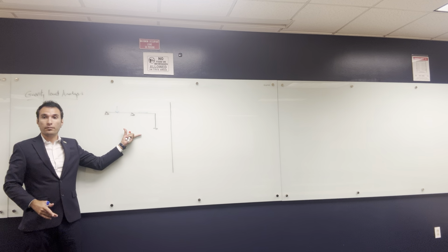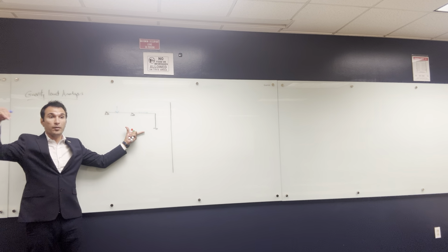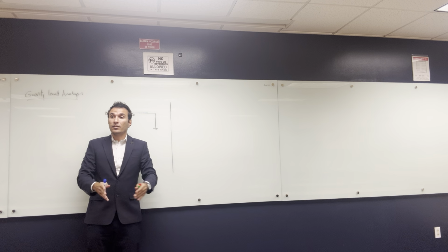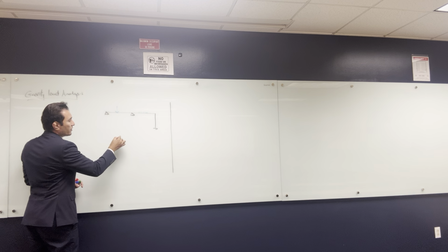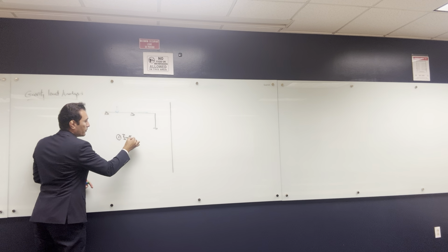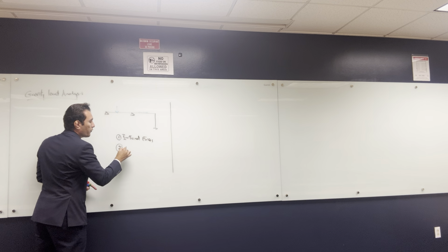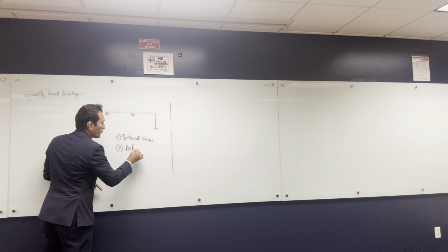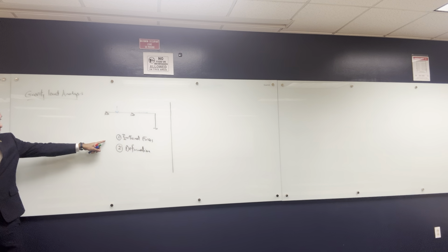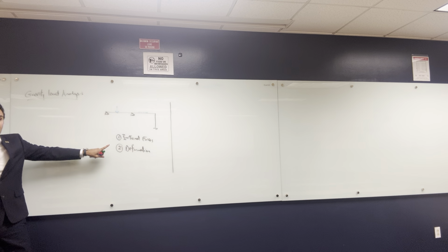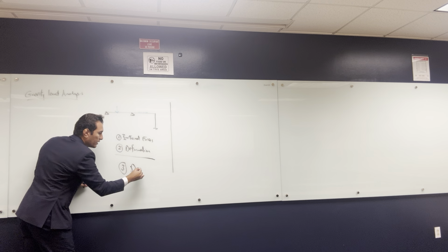First, you build the system. Choose the system, flat slab, solid slab, whatever the system is. I build the system, I put the loads, I do analysis of the system, and once I do analysis of the system, I get two things. First, internal forces. Second is deformations. That's what we do in our design as structural engineers. We are only looking for internal forces and deformations, and then in other courses you will learn design.